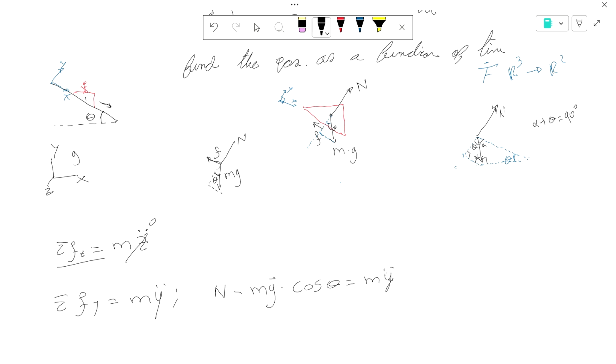All right, so the next thing we need to do is, well, first of all, this is y. Acceleration across y: if we say that it is not accelerating on y, because there's only one axis of displacement, which is on x, then we can say that this is 0 and this is just like statics. The summation of forces equals 0, then my normal force is equal to the mass of my system times the gravity times cosine of theta.